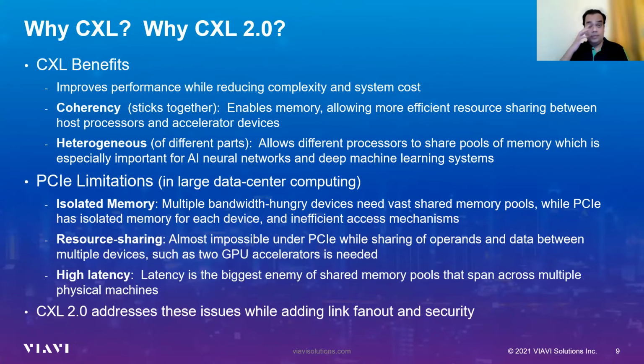Why CXL and why CXL 2.0? The main benefit, as I mentioned, is to improve performance, but in a system with proper implementation. It should also allow for reducing complexity and even system cost while improving your flexibility. To do that, CXL defines coherency to enable memory pools that are consistent in terms of validity of data, which allows more efficient and faster resource sharing between devices and processors.